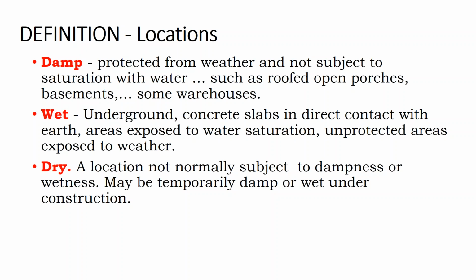But a thicker jacket up on a rooftop has some other advantages. If a squirrel chews on your wire, a little bit of thicker jacket might save you. If you're pulling cable under the array and you're not doing good cable management, and you've caught the edge of a metal conduit or fitting or racking with your solar cable, and then over time the racking is expanding and contracting with temperature, and that rack is tugging on your cable or rubbing into the cable, a little bit of a thicker jacket might be what saves you from ground faulting.